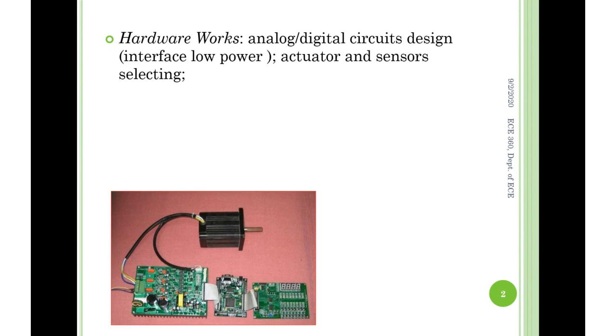What signal is the controller board providing back to the power board through the ribbon? Anyone else? Duty cycle modulation. Very good. Modulation. PWM. Excellent. The controller board is obviously implementing the control through the PWM signal. That PWM signal goes through this ribbon cable with very low power and reaches the power circuit, and the power circuit has a sort of amplification to make the PWM strong enough to drive what?